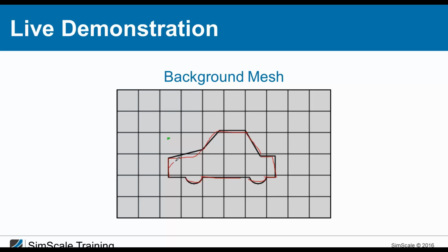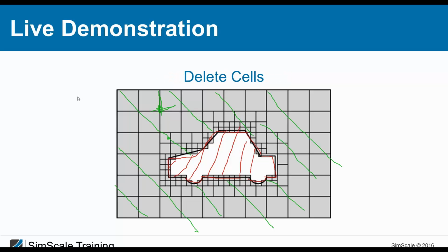We have one mesh, I make it red, the inner mesh, and we have the outer mesh, which is outside, ending here. And based on where your material point is, the tool will decide which part of the mesh it should delete. If your material point is here, then the inner part of the mesh will be deleted, and if it's inside, the other way around. I hope you got it, Rahul.